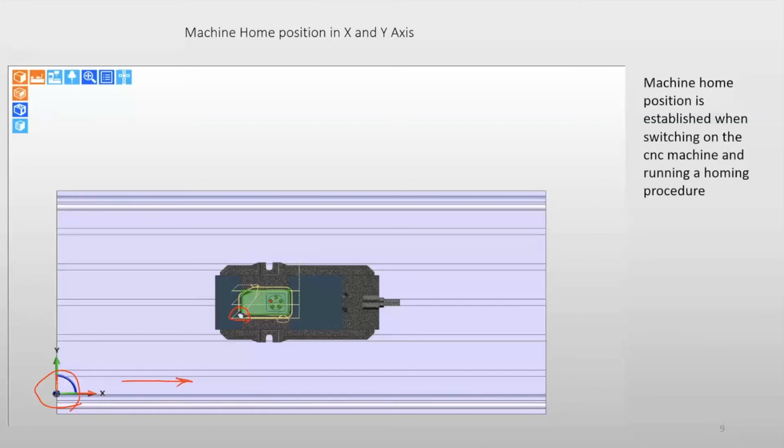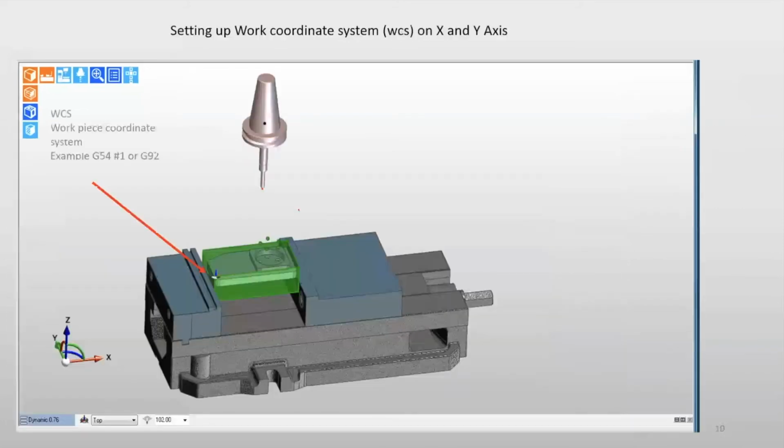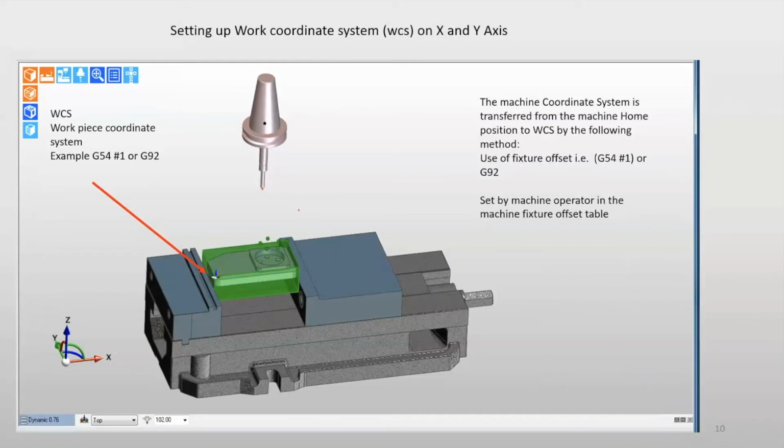So what I need to do is bring it first to there, make the machine zero, X0, Y0, Z0, and then I start doing the operation. So that's one of the things we need to do in there. And in terms of the coding, it's G54. It could always be written G92, but G54 is usually what we write to make sure we actually zero the machine.